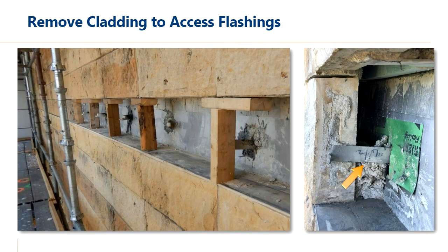So here are some photos of construction. On the left, you have the stone removed with some of the wall anchors exposed. So those hold the stone back from kind of leaning out forward over time. And those penetrate a 2-component through-wall flashing. So the top piece is a counter flashing, and the bottom is your sheet metal flashing over your shelf angle.